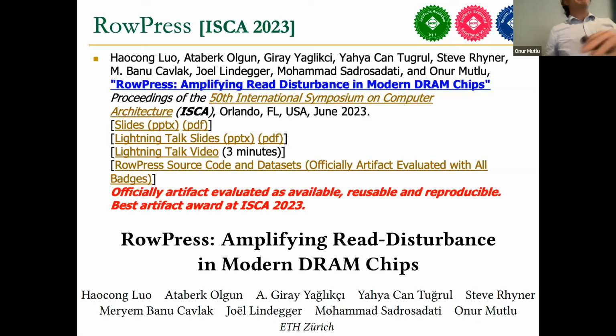Okay, maybe we can talk about the device level issues later on. I wanted to keep the abstraction level higher, but there are a lot of interesting things, and people are also examining this. People are trying to model this using TCAD simulations, etc. It's not easy, essentially. But those two things I mentioned earlier, crosstalk and electromigration, are the two major mechanisms that we know of that lead to RowHammer. RowPress is the passing gate effect, essentially.